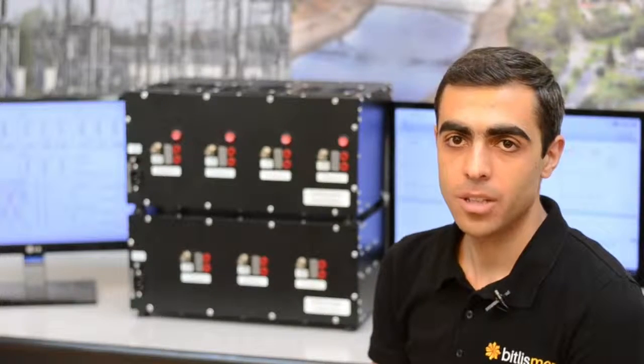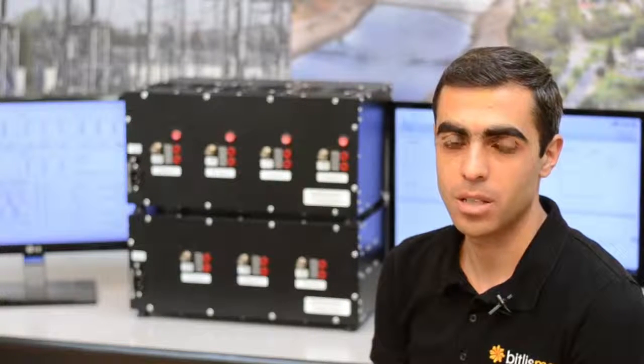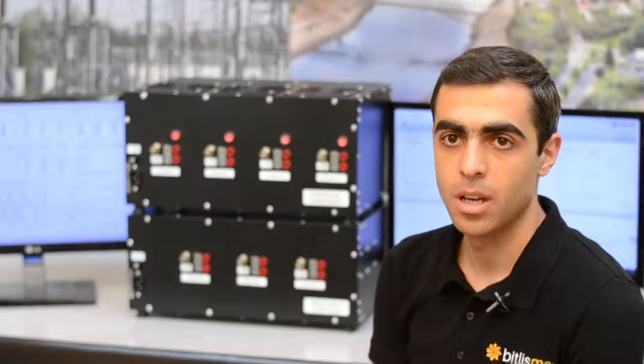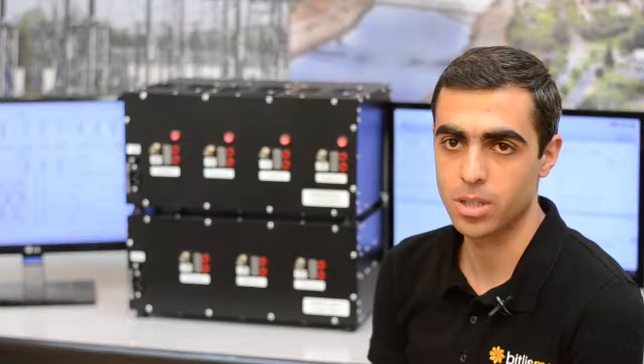The NETSimulator simulates real high voltage and high current signals. It can be used in university labs, vocational colleges and research universities as a simulator of voltage and current transformers, based on which various labs can be created. Another application of NETSimulator is the testing of various power metering devices and microprocessor-based relays. For this case, NETSimulator API should be used for loopback acquisition and testing.